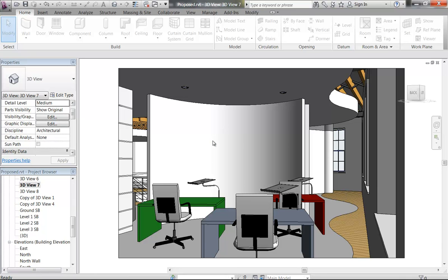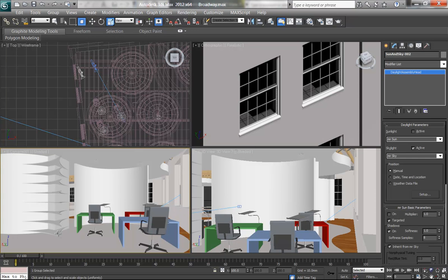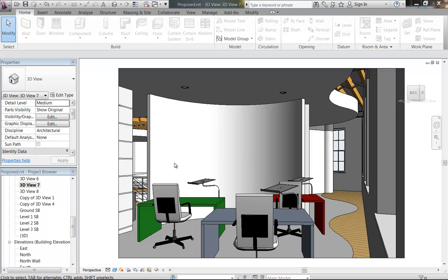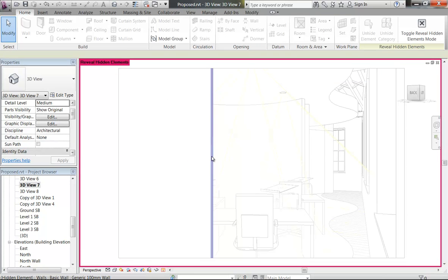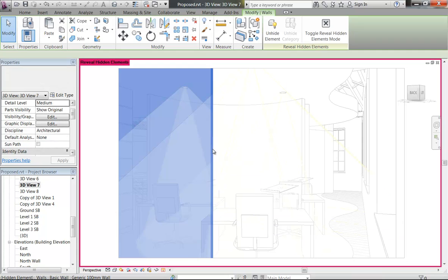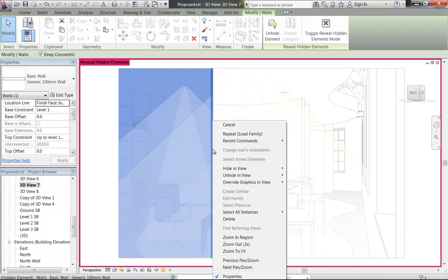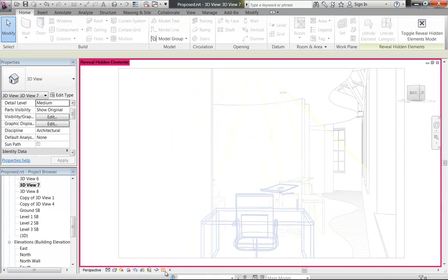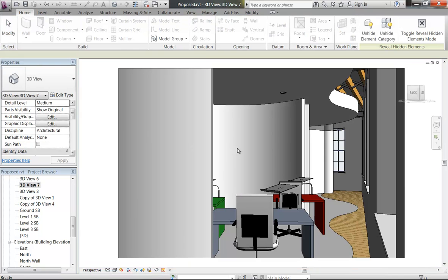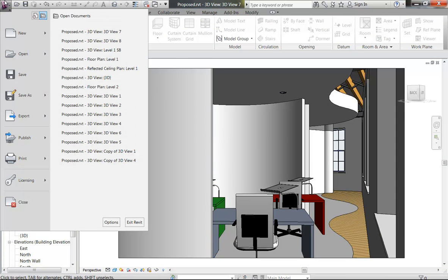Oh, and sorry, there is one other thing. The wall. Did you notice how here we can't see that wall? Well, why not? I don't mind the shelves like that actually. So it's one of those things where sometimes you make a mistake and realise it can look pretty good, but I do want the wall. So in my 3D view, you can see I've hidden it. That's a bit of a cheat you can use in Revit sometimes, but now I want it back. So I'm going to unhide in view elements, and then back to normal. Okay, and so now I'm going to export that yet again.